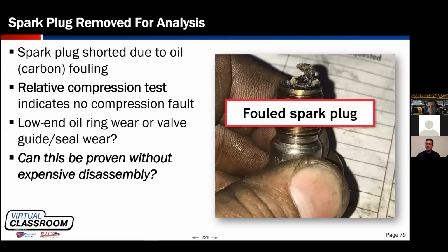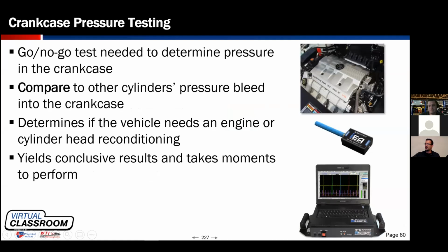So what I'm going to do now is take my pressure transducer and put it on the engine somewhere right down here where the dipstick tube is. And I could use a delta sensor, right? The delta sensor reflects change very easily. So we're not looking for a huge change in pressure as far as amplitude goes, a pressure value. But I do want to look at the delta sensor because it could show me a rapid change in pressure. In this case, I'm using the ATS inches of water sensor, which works very similarly.